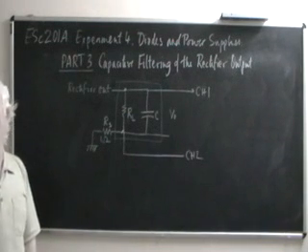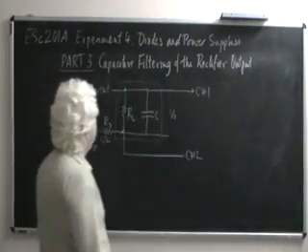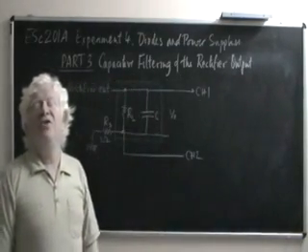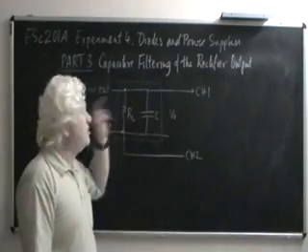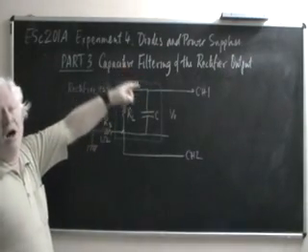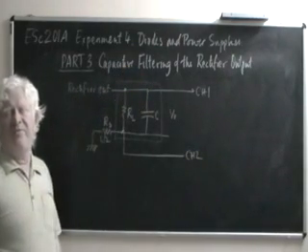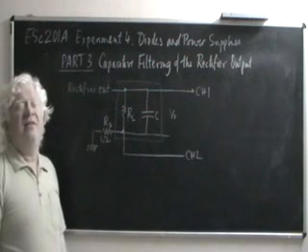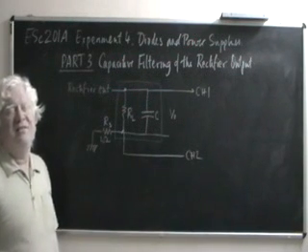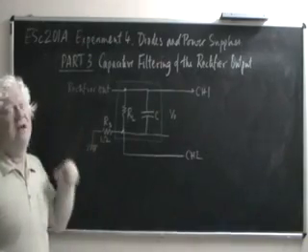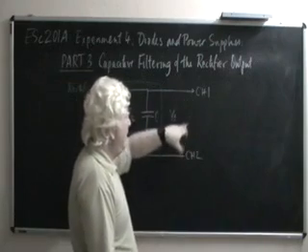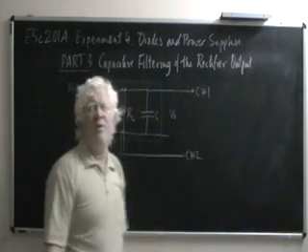What, however, is happening is that the voltage that is measured by channel 1 is not really the voltage across RL. It is the voltage across RL plus Rs, and that is not accurately the output voltage. It would therefore have been ideal to put a difference amplifier between these 2 points and send that to channel 1.